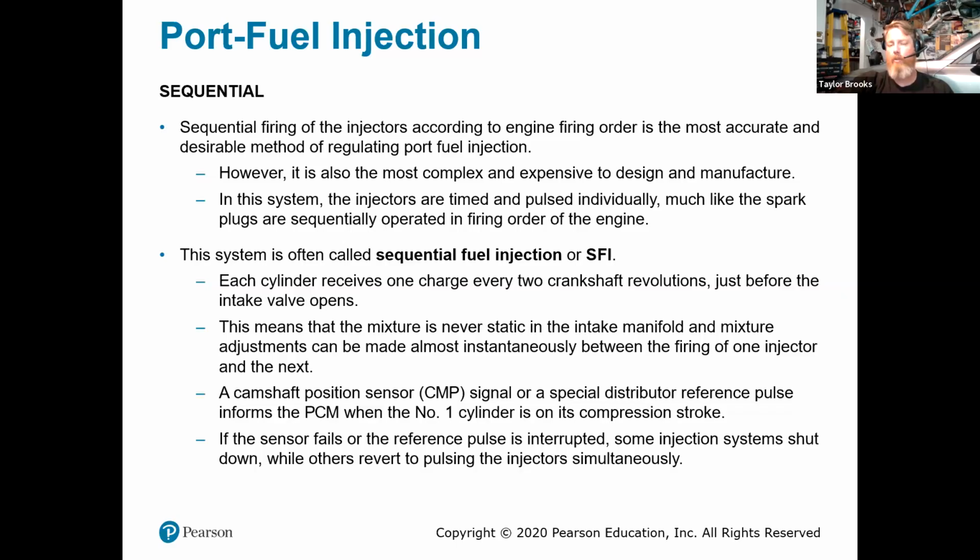We're going to match when the cylinder is about to open the intake valve to start firing the fuel injector, so that right at the intake stroke, when the intake valve is open, we are spraying fuel and there's already a small amount. Typically, it's going to be a little bit more advanced of the intake valve opening, so that it can start to do the tumble swirl. And it's going to go down into the combustion chamber, and we just have to spray the amount that's necessary to meet that stoichiometric 14.7 to 1 ratio.